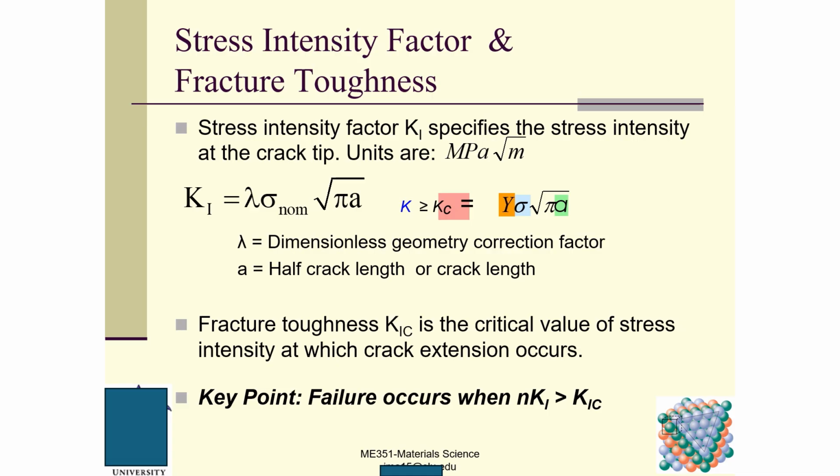You should know that stress intensity factor is exclusively related to fracture mechanics. Okay, so it is a concept in the context of fracture mechanics. You understand? This is a new concept. I want you to underscore it and pay more attention to it to expand your knowledge database. And then we talk about the fracture toughness. For the stress intensity factor K, we focus on mode 1, the opening mode. So this is K1, KI.